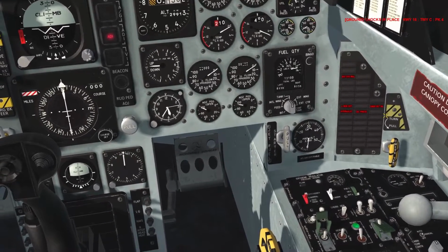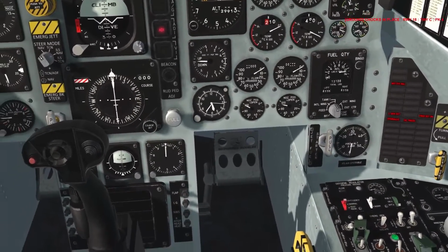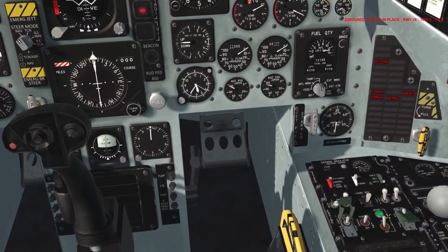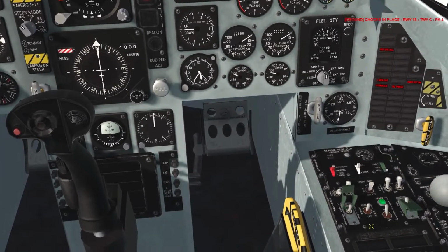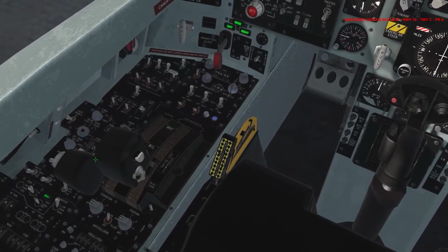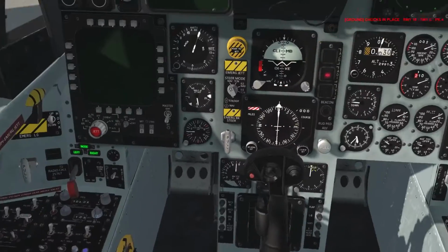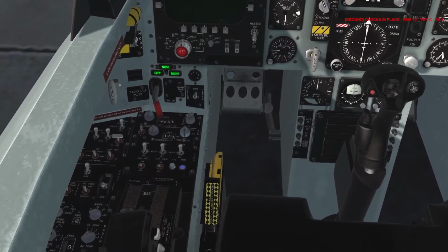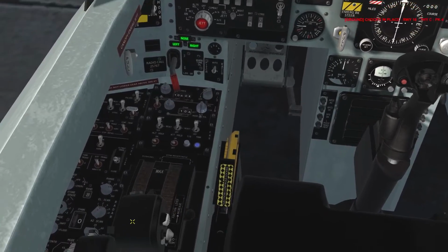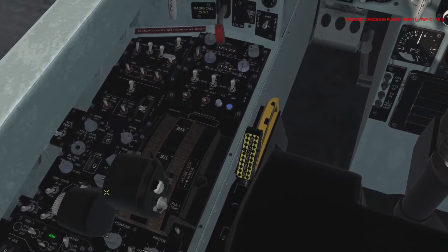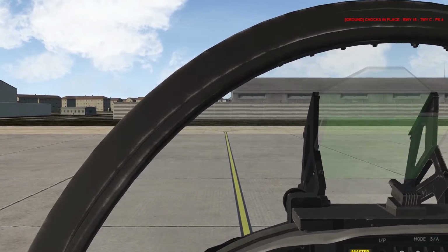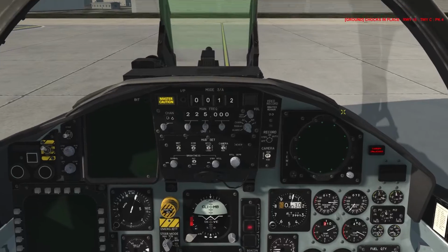That's this guy here. So other engine start. Confirm the JFS is on, JFS start ready, on, and the left engine master can come on, left generator on, and we can depress or lift and release the left engine finger lifts. You can depress the middle mouse button to pan the view around, which is handy, even though you can click it from inside or by looking through the right throttle, and then all you need to do is tap the middle mouse button to recenter your view.